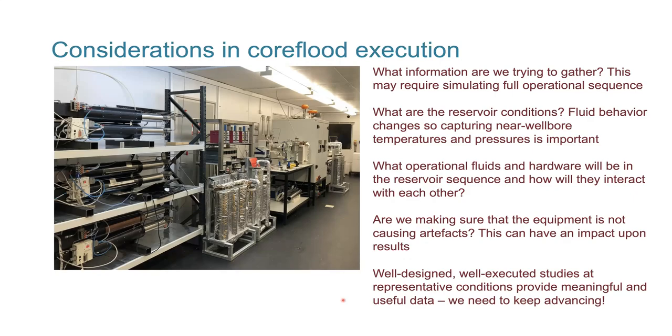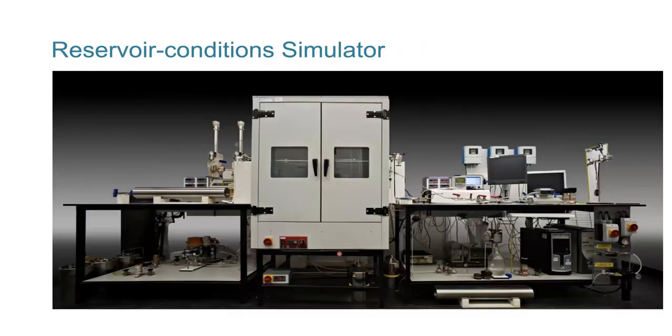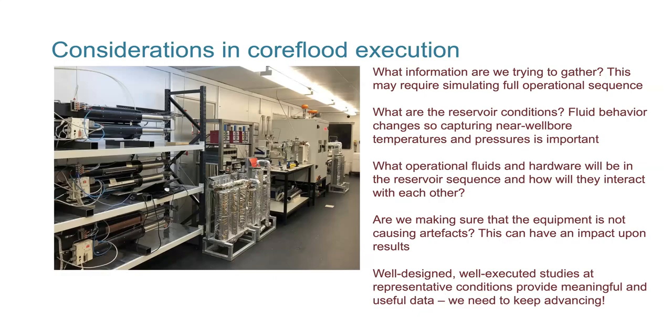So I'm showing you some pictures of, I showed you a typical test rig there. This is a kind of high-tech one here, where you can see that's the same type of piece of equipment here. But then thinking about things like production, it's very easy to say, we'll just flow oil through a core sample. But in high permeability reservoirs, flowing oil at a high rate through it might actually end up, you're not able to heat it up properly. So you might hit cold oil in the sample, which creates an artifact. So I'm showing you a bit of equipment here that allows proper heating of oil before it hits a high rate or a high permeability sample.